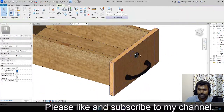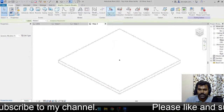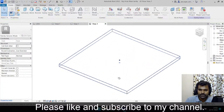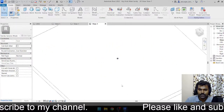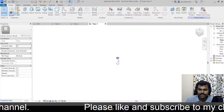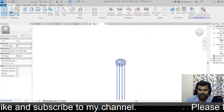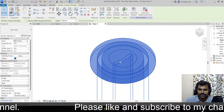Okay, so keyhole, if we select this keyhole, if I go to edit family, you can see I have used a face based family. So when you are using a face based family, you can apply some void to cut the material, cut the surface. So that's what I have done here. And if I select this piece, this is another nested family.